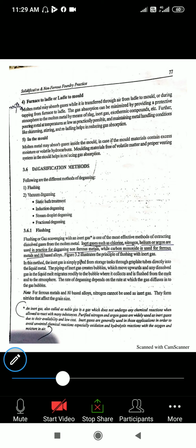So for prevention, what has to be done before pouring the molten metal is that the mold cavity is preheated. A fire flame is introduced into the mold cavity by way of the runner or the riser, which hits the mold cavity and releases all the moisture particles, so that the percentage of gas released by the moisture is reduced. So these are some of the preventions and the sources of gas generated in the mold cavity.